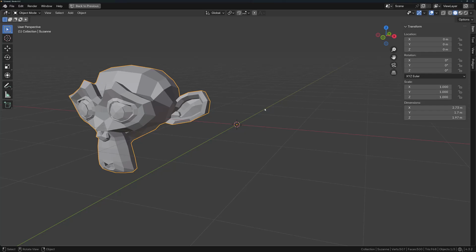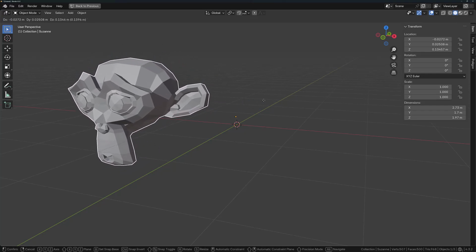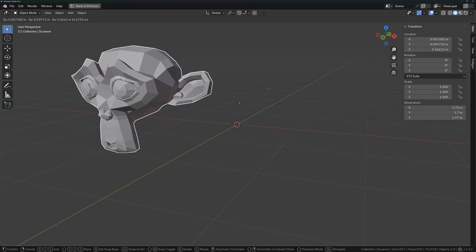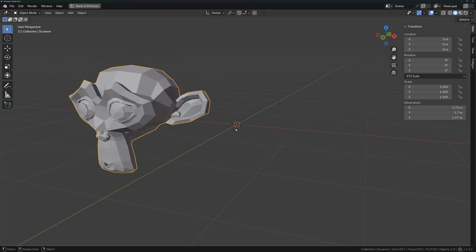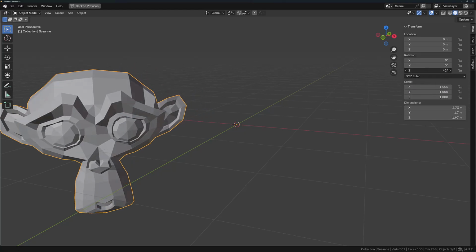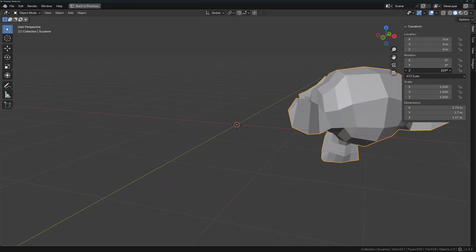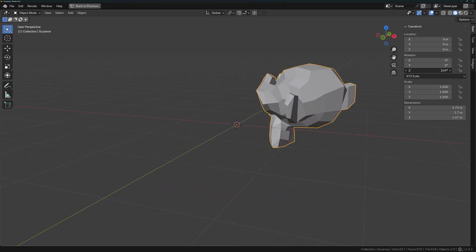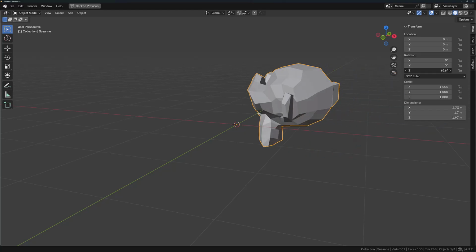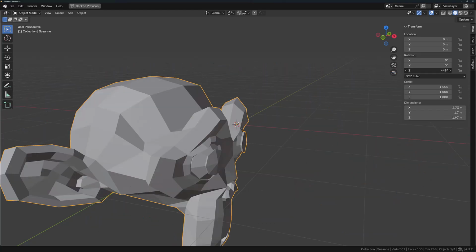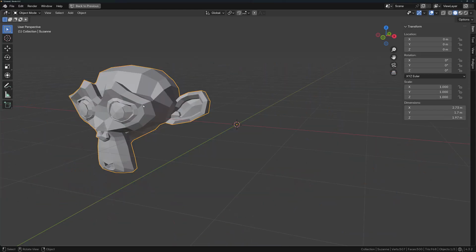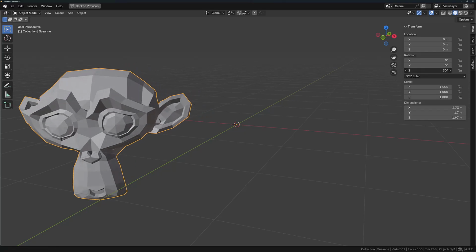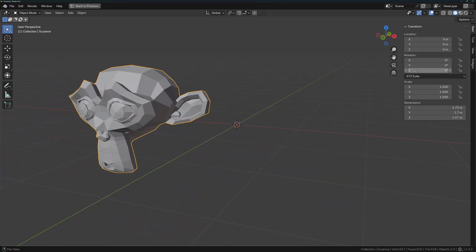Now, if I was to hit the G key in object mode, you would see that both the geometry and the object origin move in the same way, but they maintain the distance between them. Where the behavior really changes is when we use rotation and scale. For example, if I was to rotate on the z-axis, you can see now that the mesh geometry is effectively orbiting the object origin, and it also rotates the geometry itself as we change its positioning.